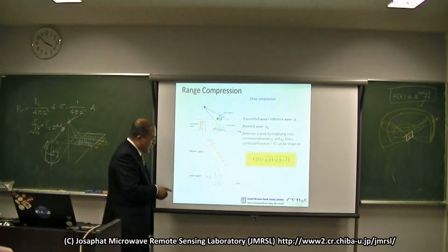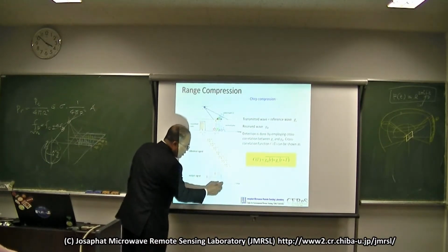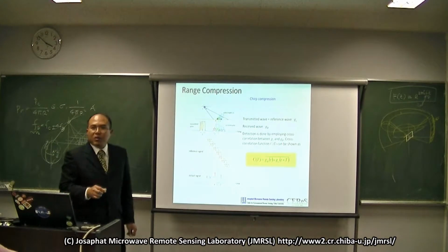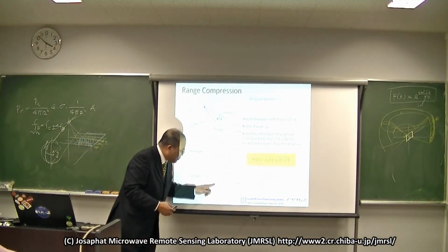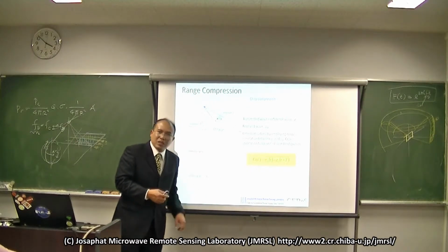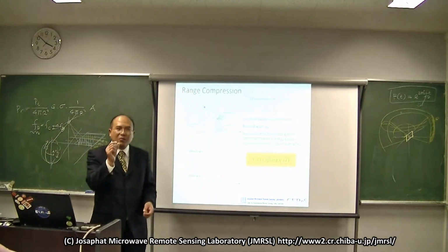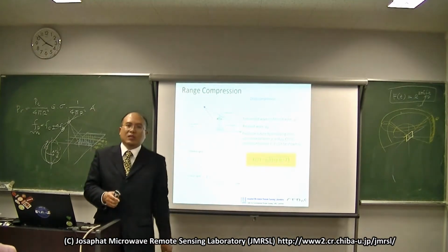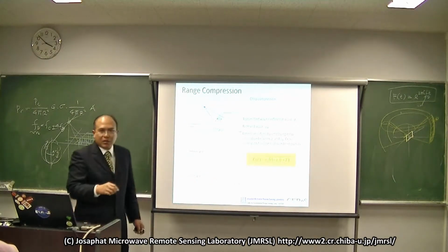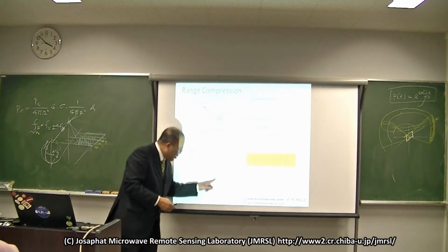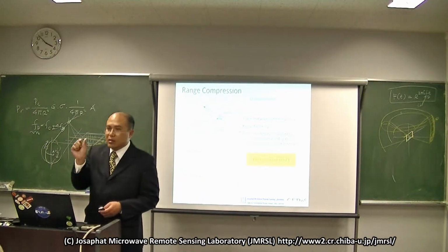And then later you can check that from A, B, C, the responses are very close. But you can discriminate the response from A, from B, from C. So this distance you can define as the resolution. The resolution itself, in the mathematical calculation, is 1 divided by delta f. Okay?